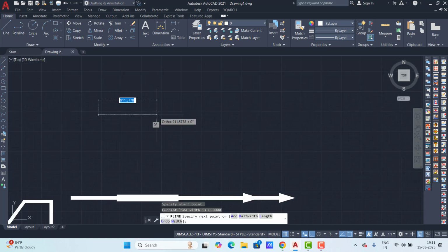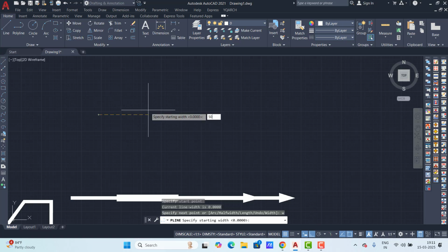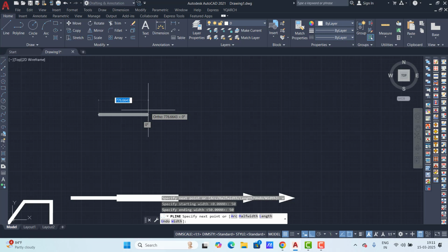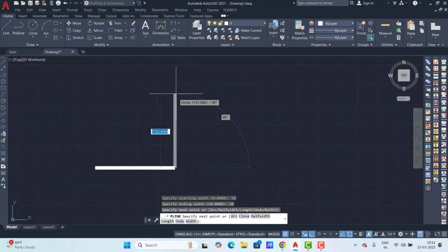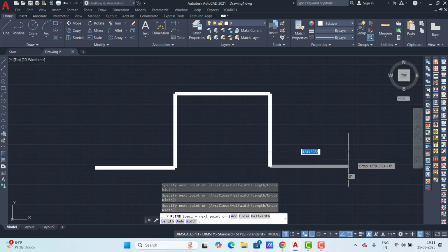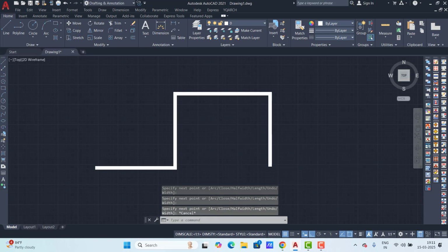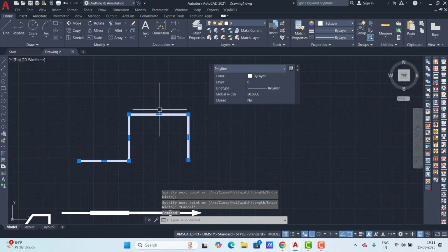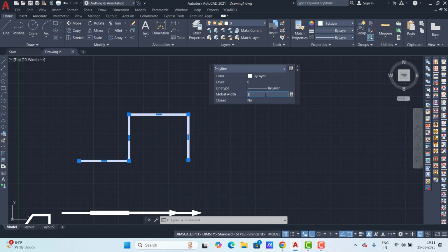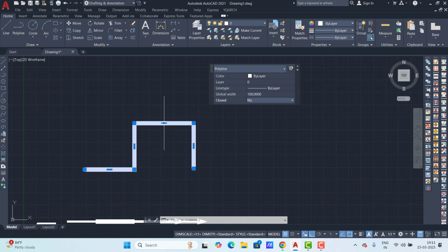Now when I select this object, there is a midpoint and an end point here and here. If you hover the cursor on the midpoint, three options show: stretch, add vertex, convert to arc. If you select the stretch option and click, you can stretch this line this way. If you click on add vertex, the line is divided into two parts. If you want to convert it into an arc, select convert to arc, so that it is converted to an arc. If you hover again, there is convert to line, and the arc converts back to a line. These are the additional properties in polyline.